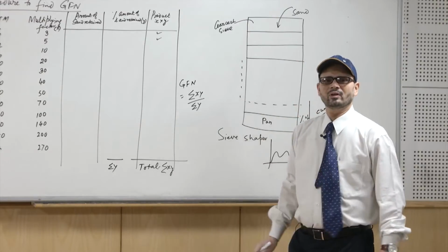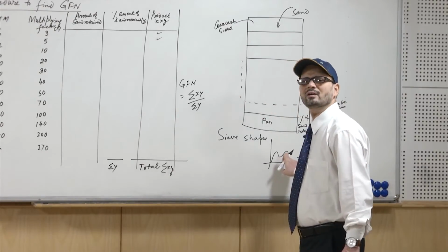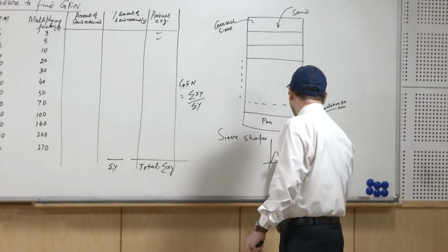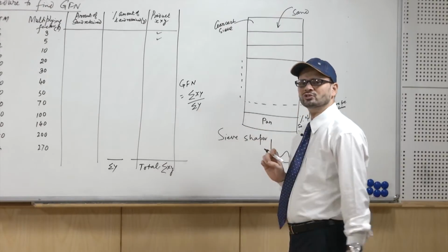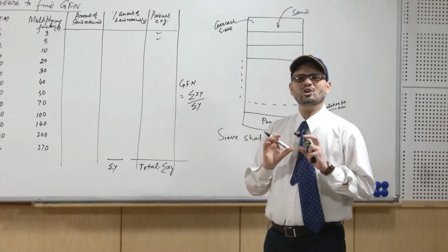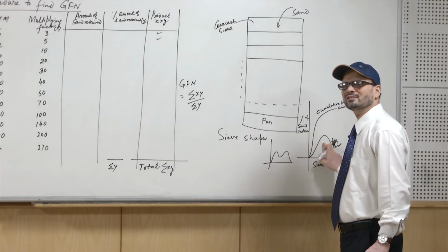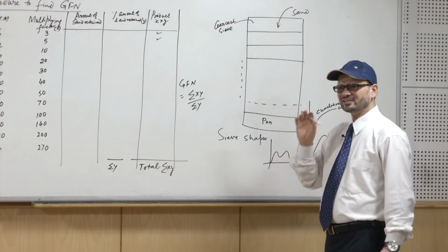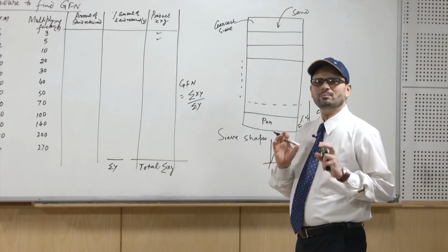There may be even two peaks, the curve may be like that, which is a bimodal type of curve, and basically it tells that there is a mixture where some is very fine and some is very coarse. So, these types of curves are not desirable. We must have a unimodal type of frequency curve, and this indicates that the size distribution is proper.